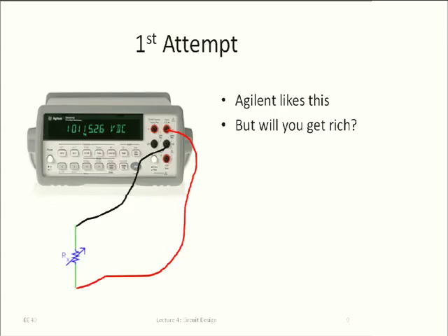So the first step really should be something very simple, something that figures out, is it even possible to do that? For example, I have now such a strain resistor, and notice I went back to a circuit schematic kind of description. Let's figure out whether the resistance really increases, right? After all, this is all a big theory. That sounds great and nice, but does it really work? So we have the lab instrument, and we can connect it and measure that resistance. We can pull on the resistor and see whether the resistance actually goes up. Incidentally, here this shouldn't say volts, this should say ohm.